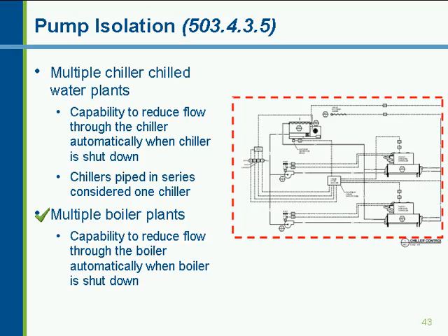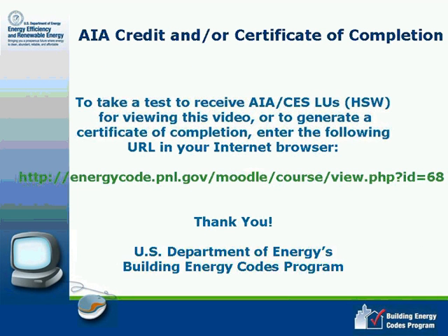Okay, there was a question about, I mentioned the types of exceptions for energy recovery ventilation systems per the IMC. Can you state some of those again? I just gave 2 examples, and I don't have the IMC with me, so whoever wants to verify this should probably check. But I believe that the IMC has a prohibition against doing heat recovery from systems that are exhausting toxic fumes and from kitchen grease hoods as well. But that should probably be verified, but I believe that's correct.